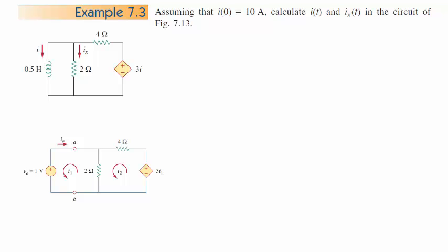Now there are two ways you can solve this problem. One is by finding the Thevenin equivalent, because first of all I have to get it into the form of being an R and an L, right? And I have this dependent source in here throwing me off. So if I'm going to find a Thevenin equivalent, that's method 1, then I need to find the equivalent resistance as seen by the load, and the load is the inductor, because I want to get an equivalent resistance over here. So that's method number 1.